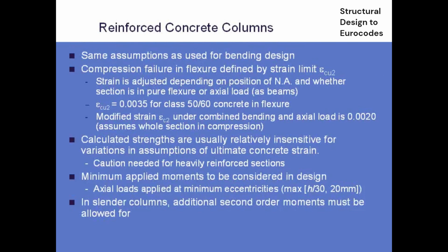That horrible diagram with the pivot point that we mentioned applies in that situation, but as I mentioned, it doesn't make much difference, so I'm personally quite comfortable about ignoring that particular provision. Other things to know, probably notes, are that there are some minimum moments we have to consider in the design of columns.